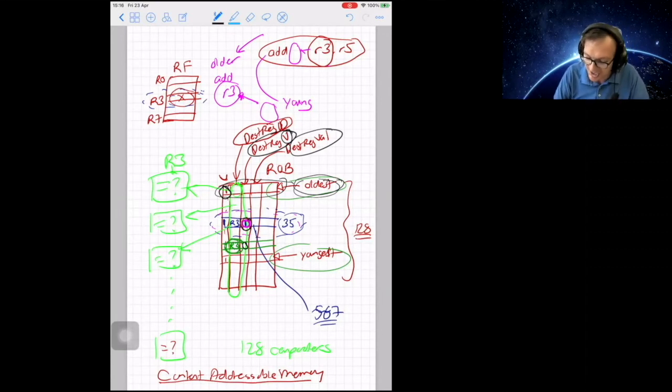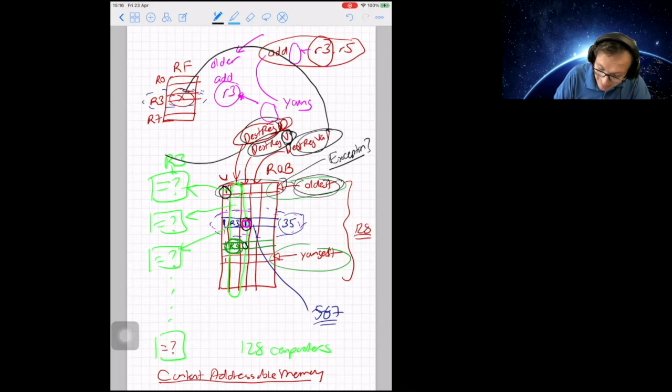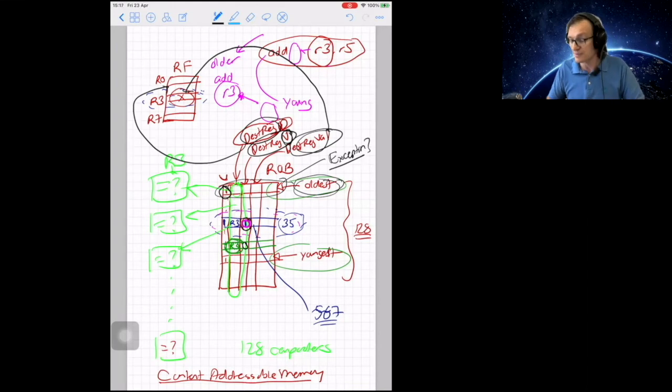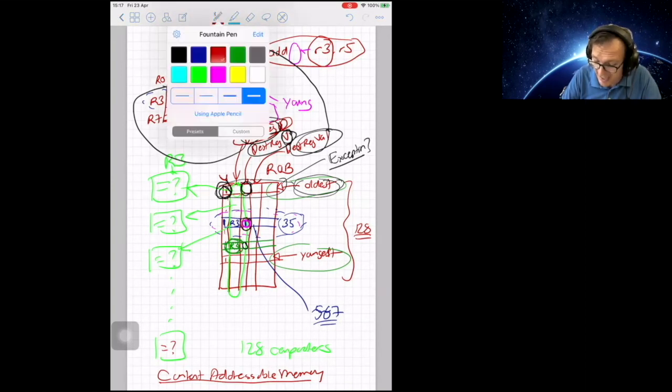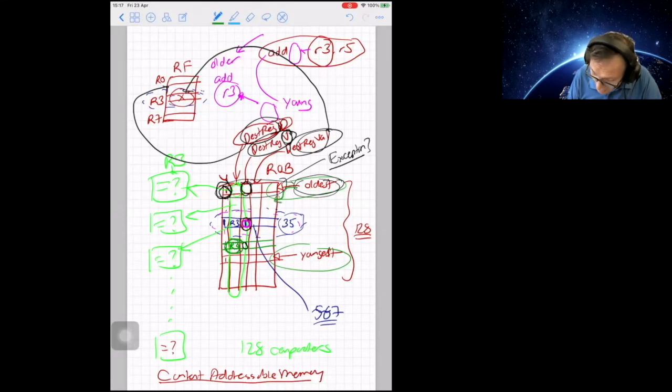Let's assume R-type instructions. Now, if it's valid, then it's finished. It also checks whether there's an exception from the instruction. And if this exception is set to none, then you can take the destination register value and write it to the destination register ID, whatever that ID specifies. Assuming that the instruction has written to the reorder buffer, which means its entry is valid, and also the value that's being written is valid. Then you advance the oldest pointer, and that would answer the question that your colleague asked over here. You advance the oldest pointer to here, right?